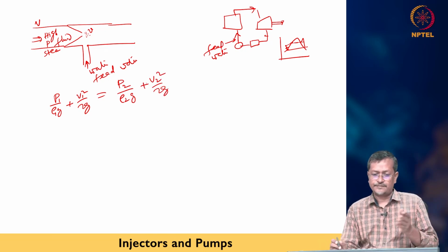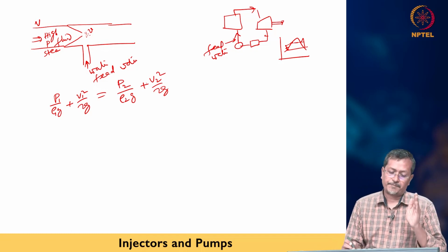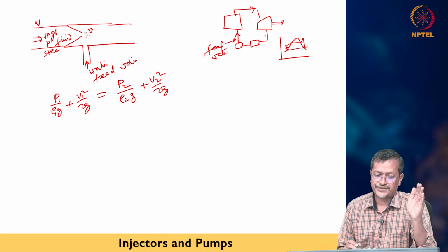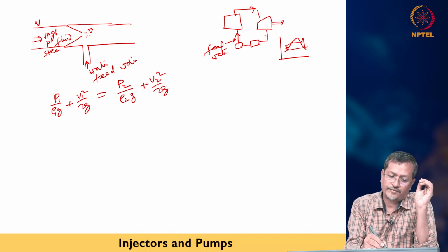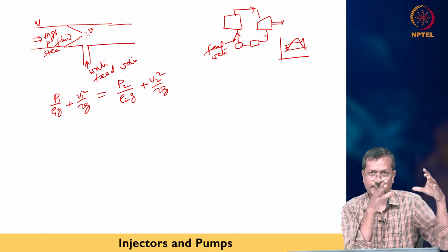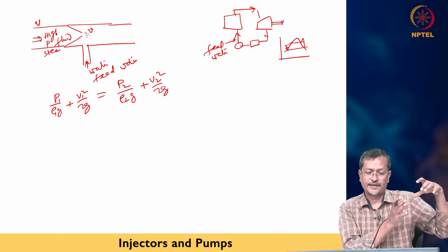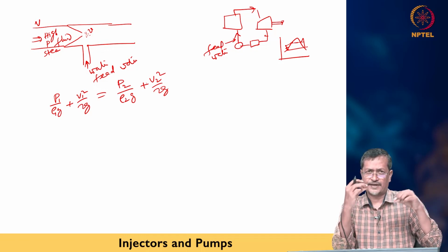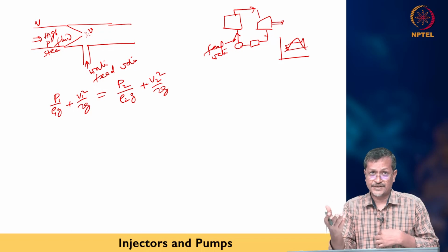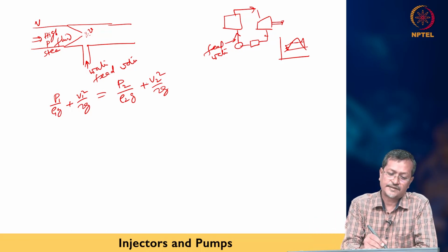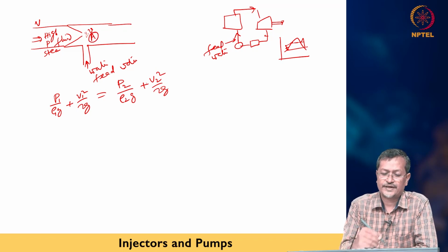Okay, you can see pressure, let us assume density constant. Now if pressure is changing, let us say initial pressure P, velocity V, velocity changing. Upstream, in the larger diameter pipe, pressure is high. Now fluid is flowing through the narrow channel. So narrow channel means velocity will be increasing. When velocity is increasing, pressure will be dropping. When pressure is dropping, this location A I marked here will have low pressure.